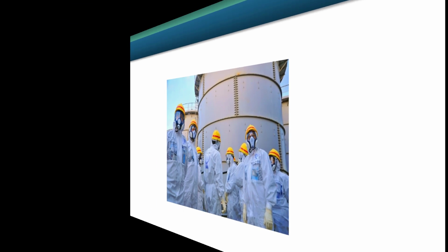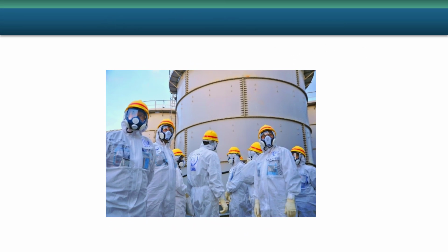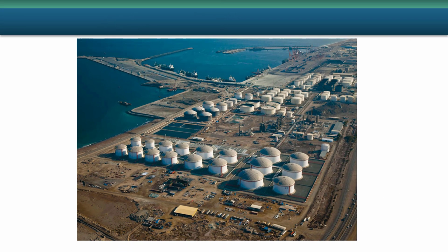Here's a bolted tank that's used in the upstream industry. This is more like a typical petroleum storage terminal. These are aluminum domes, and I want to point out that they have exactly the same function as these cone roof tanks. The purpose is to keep out the weather, the rain, the dirt, and so forth. It costs more to build these tanks, whereas open top tanks are shown here, and the floating roof just goes up and down.